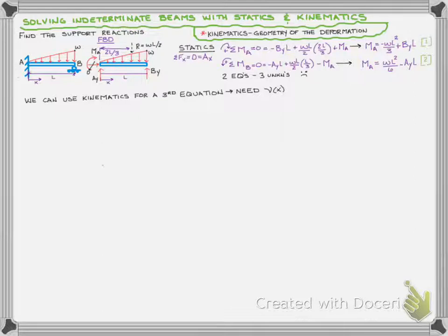So if we go back to our main beam, we can draw our deformed shape, and that's going to start out with 0 deflection at A, but also 0 slope, coming off like a diving board. Because of that moment at A, it pushes away any rotation, and we get 0 rotation, 0 slope at A. But now instead of just going off like a cantilever and having our maximum deflection at B, because of that roller, we're going to come back up and have 0 displacement also at B.